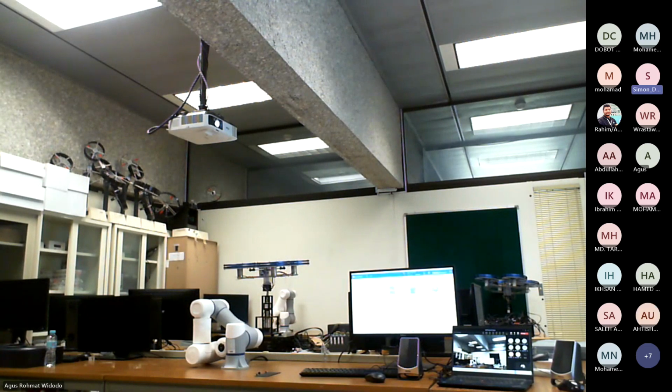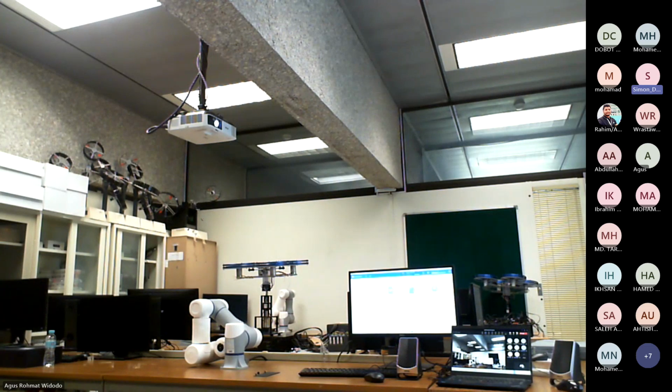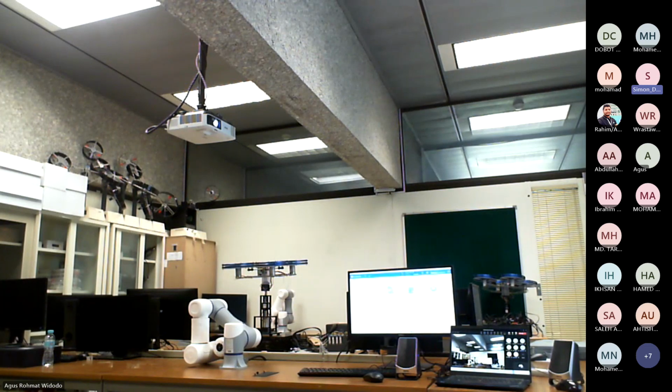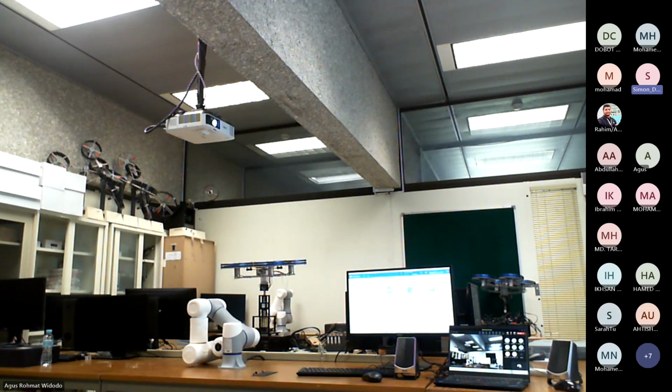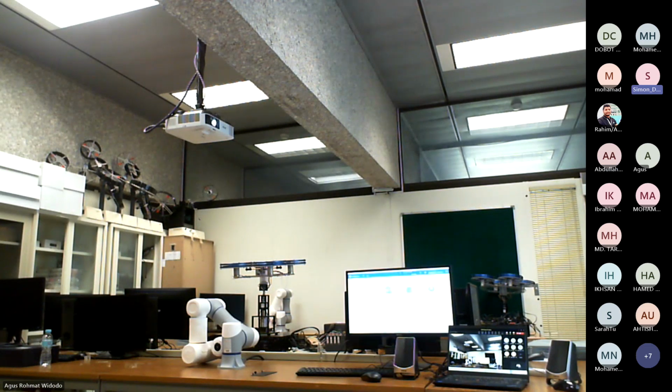Yes. On the arm, we have the collision detection. There are 5 levels of collision detection. I will introduce it in advanced training. And also on your table, there's a robot with safety skin. It's also a function of obstacle avoidance. Yeah. So there are sensors on the arm itself? Actually, we don't use sensors in the arm itself. We calculate the power, the current of the motor. So once there's any collision, when the force is bigger than some value, it will trigger the stop.